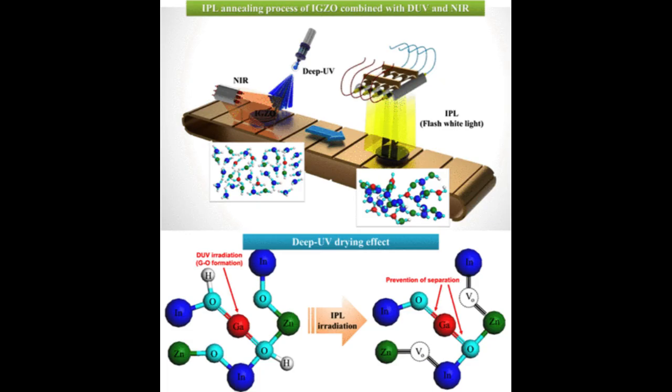8. Thermal annealing. The wafer is subjected to high temperatures in a process called annealing. This helps to activate and diffuse the dopants, making them electrically active and creating well-defined conductivity regions.